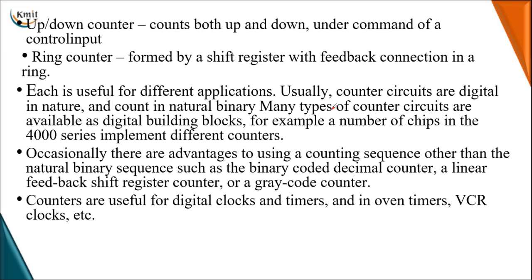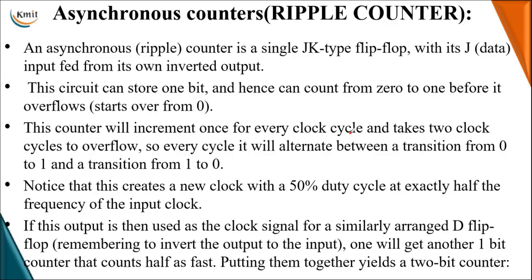We may also require an up counter or a down counter, and we can design the up counter or the down counter using only one control signal. Registers can also be converted into a counter by connecting the output of the registers back as the input, so you can construct ring counters. These many different counters are used in suitable applications. Now let me learn about the asynchronous counter.